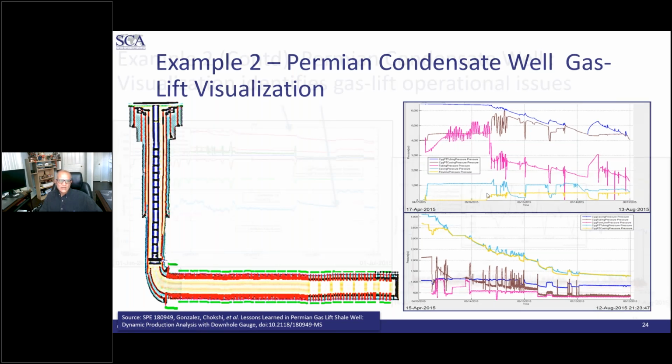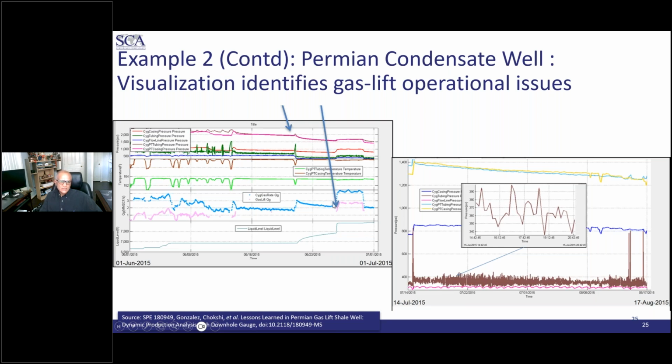And you can see, of course, that there are some changes in the injection rate and the downhole gauges. But what we saw more clearly when we zoomed in on the downhole gauges is the slugging. And this slugging often is a result of the long lateral that we have, right? Until that point, the only slugging you would see is at the surface, muted. But the moment you see this, there are some possibilities.